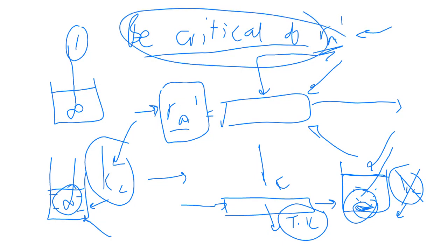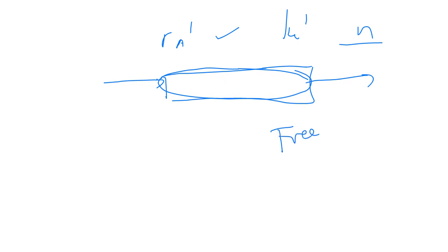That's the first point. The second point is when you now design, make sure that, okay, yes, I apply this rate. I now have a rate equation, like some of the TUTs, I have published data. I know what my intrinsic rate constant is. I know my rate order. Make sure that the reactor that you design is free of external diffusion effects. Free of it. You don't want to design a reactor where this holds back your rate.